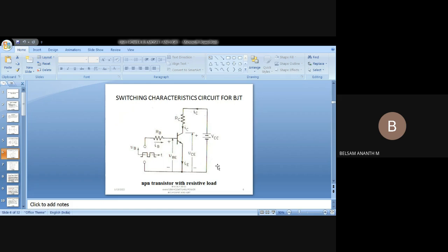When I want to turn on my device, I should give a kind of triggering, an instant signal, onto my gate. Thereby, I can make the device understand. Though I may give the supply and other things, for certain devices, for example TRIACs and SCRs, I just want to give a triggering instant of signal to my gate terminal. Please never forget that. A kind of triggering, an instant signal, I am giving, and thereby the device is converted to on.